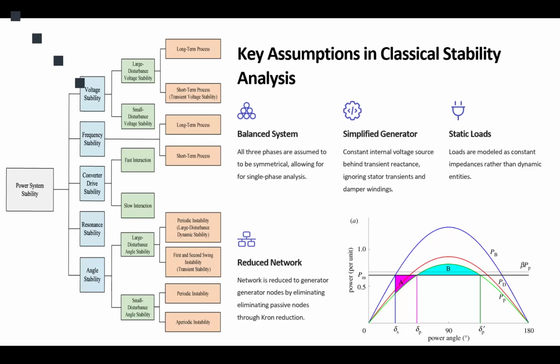So we simplify the generator model and represent it with basically an internal voltage and a reactance, instead of all the differential equations of a mechanical system and electromechanical energy conversion, like Faraday's law, Ohm's law, KVL, KCL.